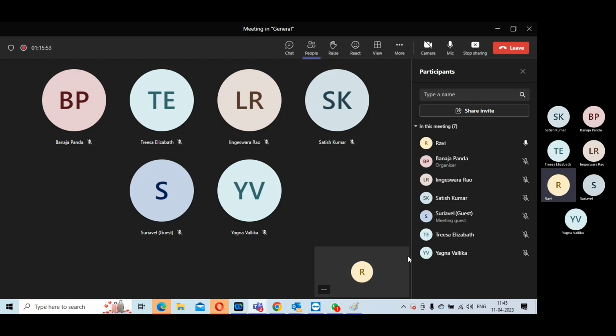GDS is dumped after the completion of the routing. That's only a wire GDS. You are dumping using the LEF, so whatever metal layers are there, but that's not your full GDS. After that, you have to add all the library GDS. That is the merging, because the library will have all the layers below M1, your silicon, then your well and implant layers; every layer has to be present. You will have to add all those layers, then you do DRC.